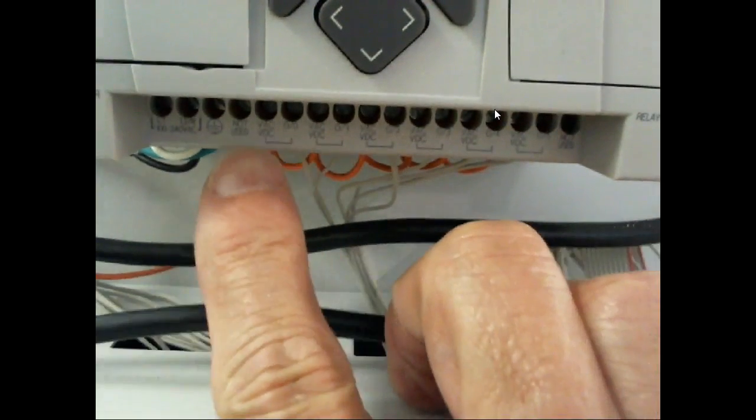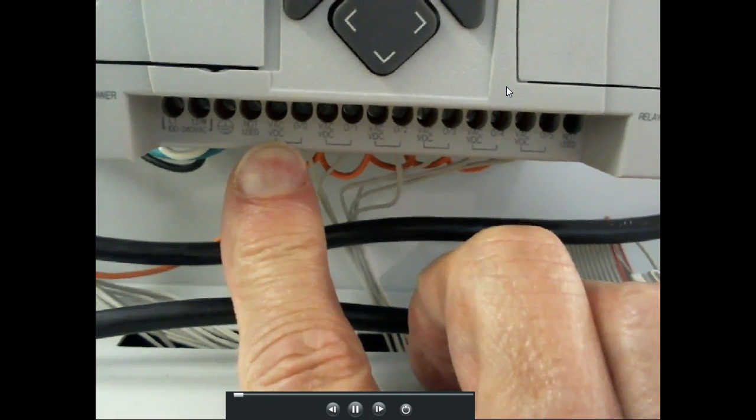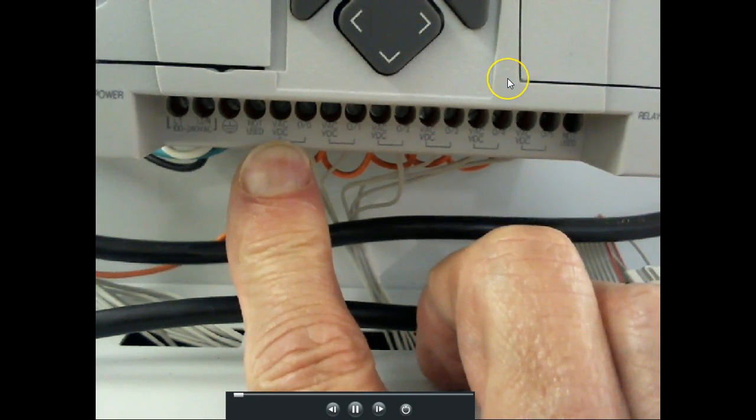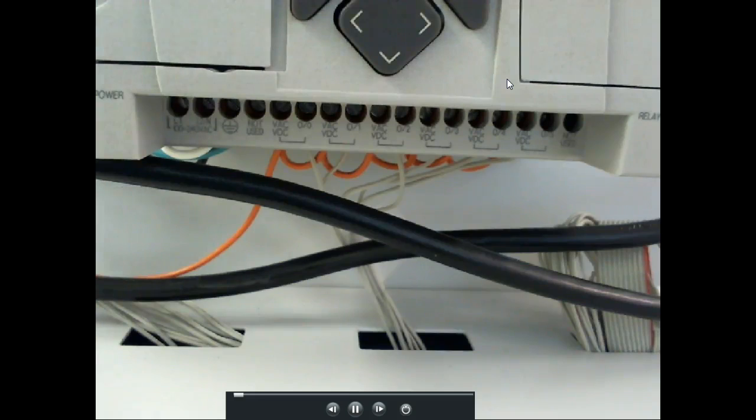So you notice what we have on every output. I don't know if y'all can see this, but it says AC or DC right there. So that's one advantage of having a relay output, that you decide what your common's going to be, right? If you're using DC, you can decide whether you want to sync or source, right? That makes sense. You can decide if you're going to use AC. If we use AC, there's no such thing as syncing and sourcing because AC has no polarity.